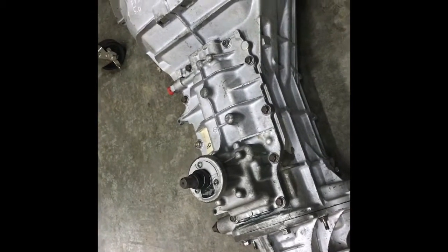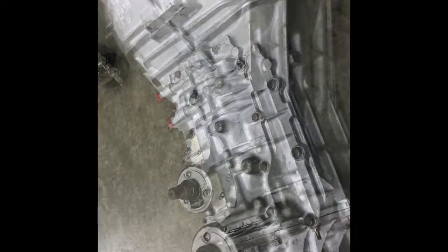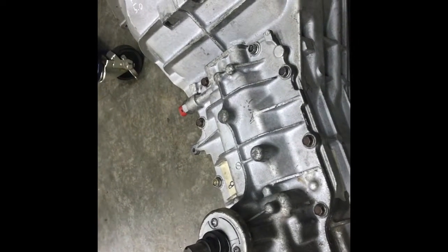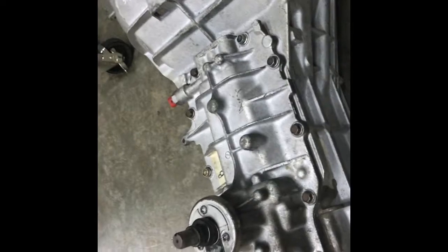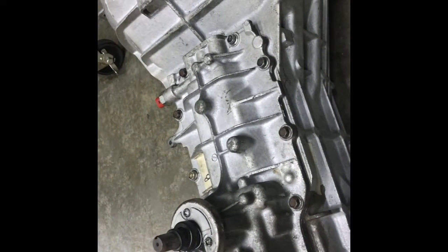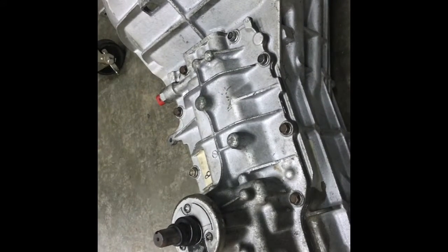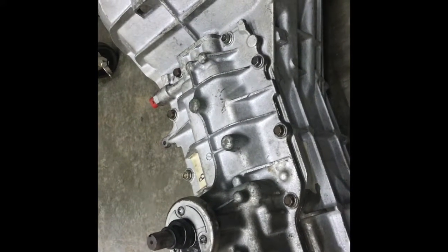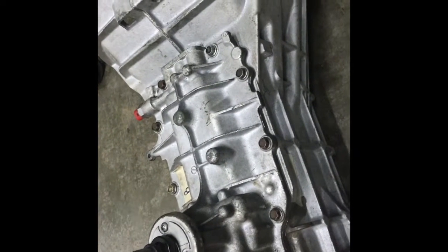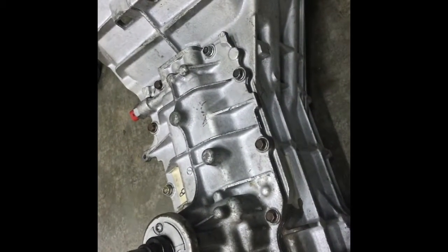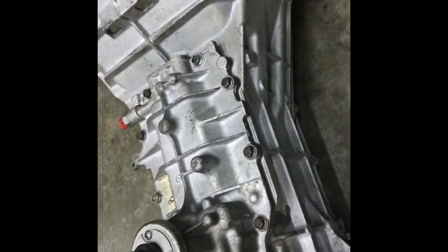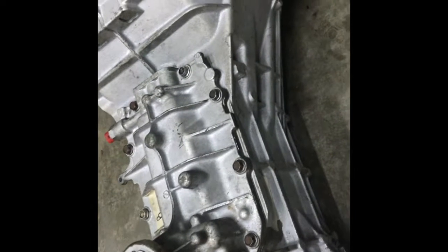This is a manual transmission. The manual transmission drivetrain consists of all the assemblies that transfer power from the engine all the way to the wheels. The clutch system is the medium by which the driver can connect and disconnect the engine from the transmission. The transmission transaxle is the medium by which the driver selects through the various gears. The final drive assembly gives the final gear reduction through the axles.